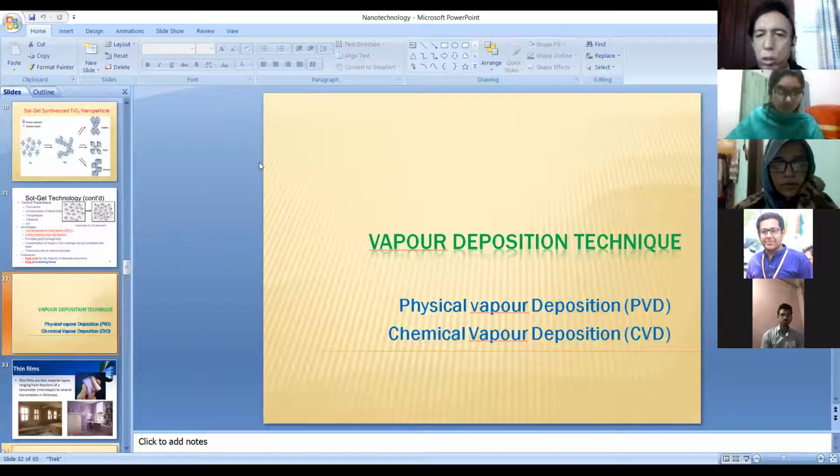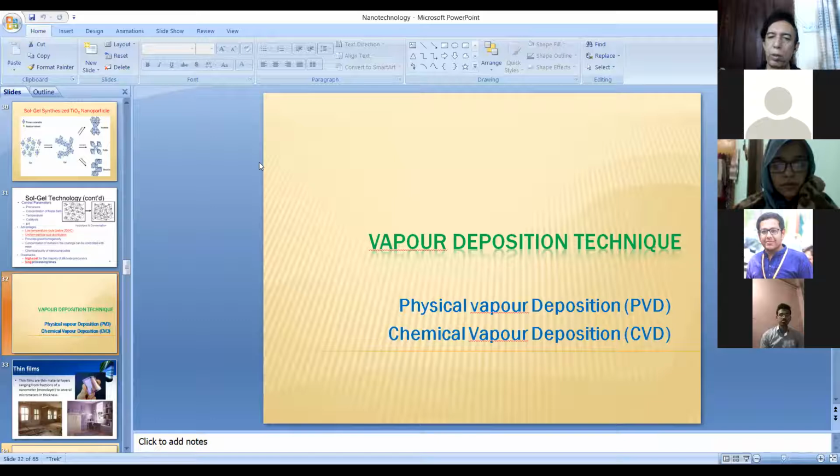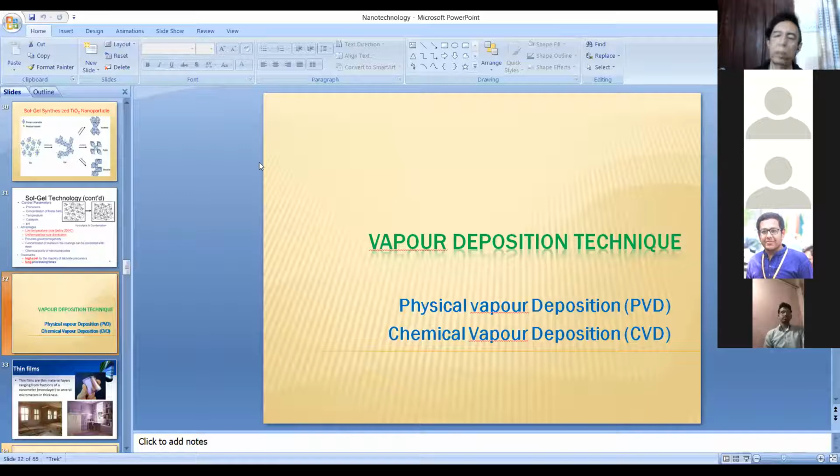Vapour deposition technique. Vapour deposition technique means we will prepare a vapor of a material. Say, for example, we shall prepare a vapor of a metal, and then we shall deposit it on a substrate.